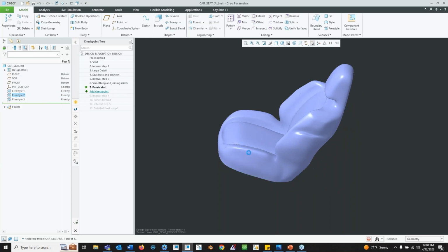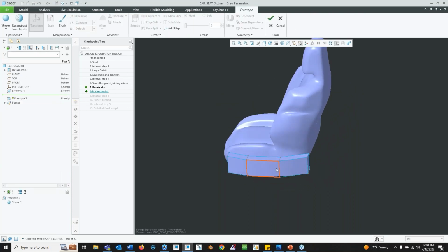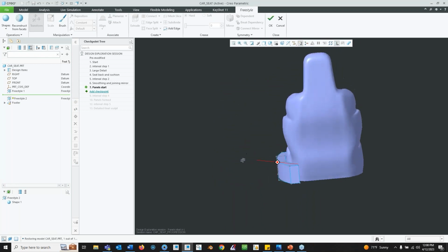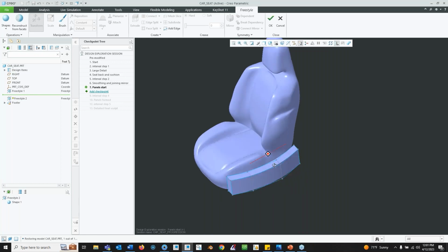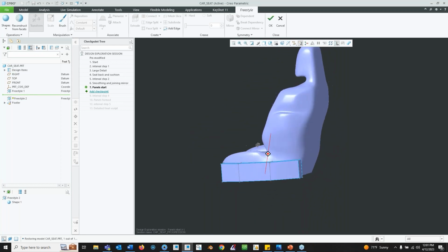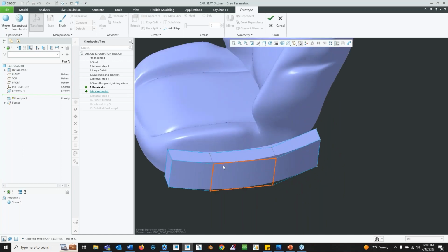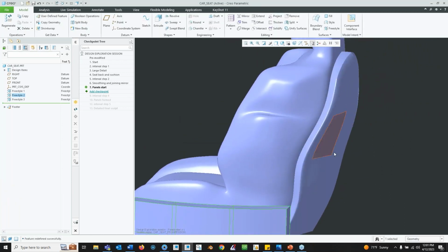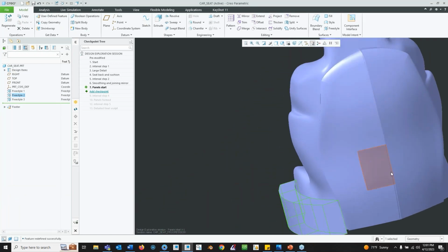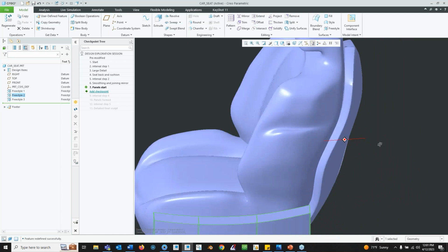And if I go in there, I'll just show you, all it was was this middle cube and two extrudes just to get the base shape down. What I like about this is that I can model around or over the existing, or the first, model. So you can have as many freestyle features in the model tree as you need, because I wanted these plastic panels to be a separate mesh. So that's just how I started with this one. I started with the cube and another cube at the back. And this one I didn't do the align or final mirror yet.